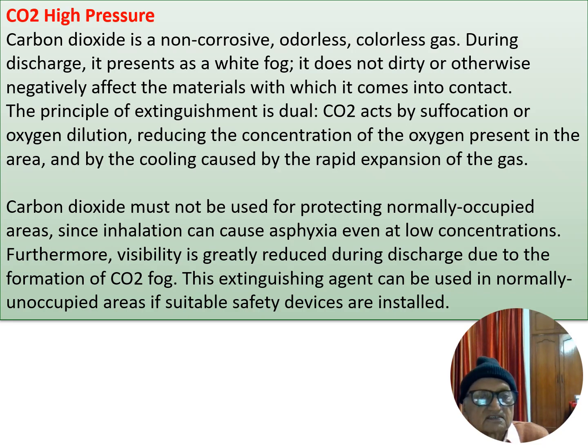Carbon dioxide is a non-corrosive, odorless and colorless gas. During discharge, it presents a white fog. It does not make the system dirty or otherwise negatively affect the materials with which it comes into contact. The principle of extinguishment is dual.